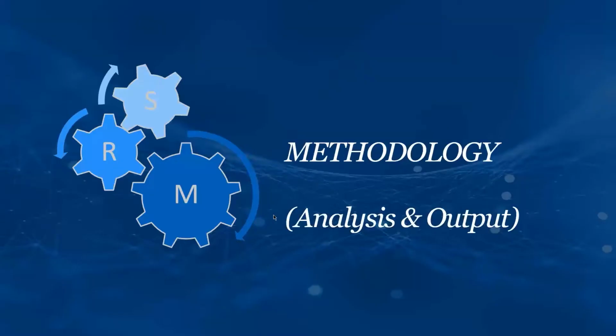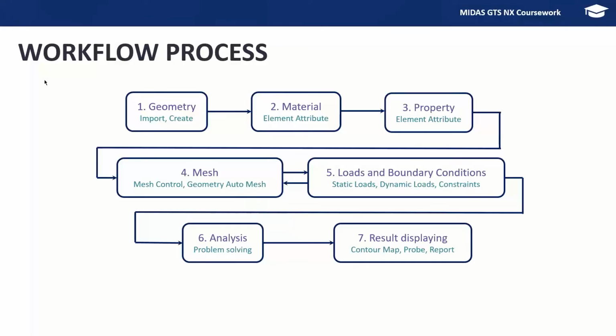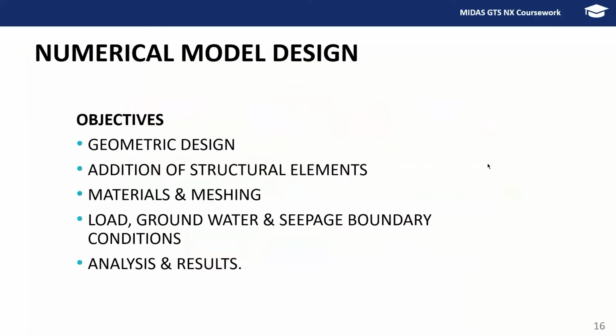So in terms of the methodology, the workflow process will always remain the same. If you have attended our previous webinars, this slide is the most common slide that you will find in all the webinars, because that is the only way you need to proceed. So you'll start with the geometry, then you go to the material properties, then you go to the definition of the element attributes, then you create the mesh, you define the loading and the boundary conditions, then you go towards the analysis or the problem solving, and finally you display the results. Okay, so next comes the numerical model design.